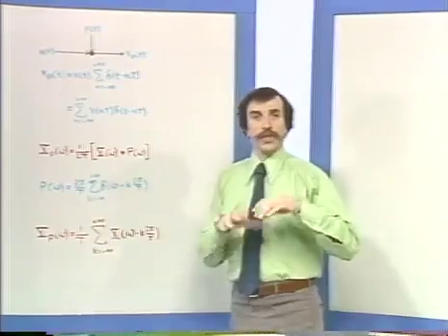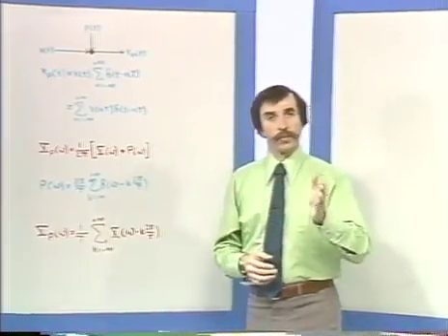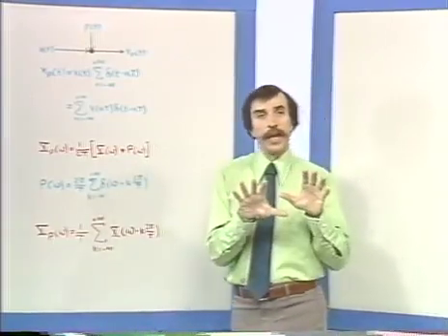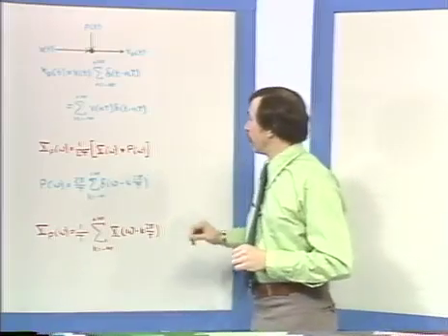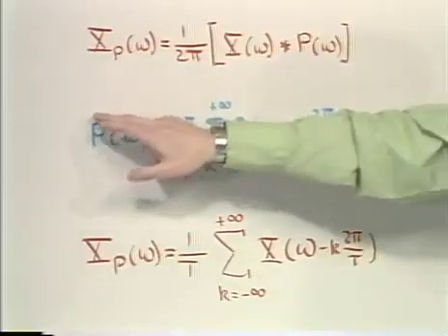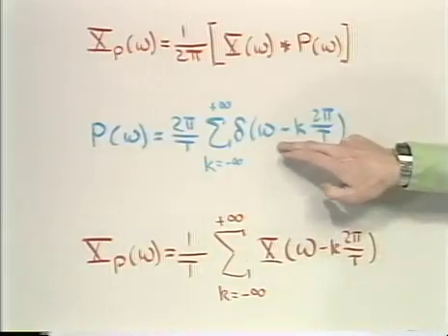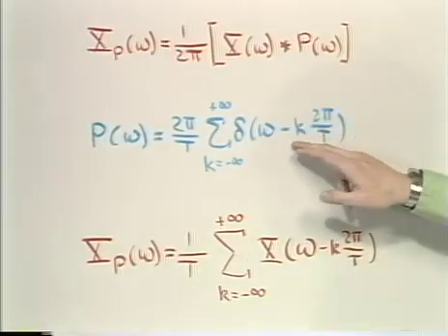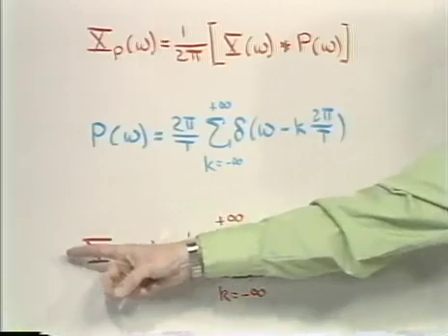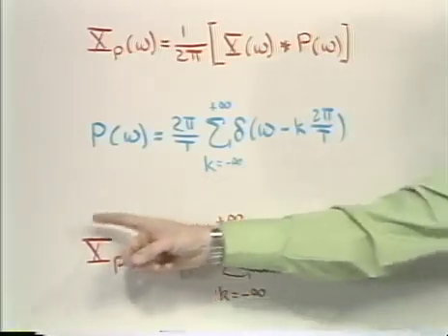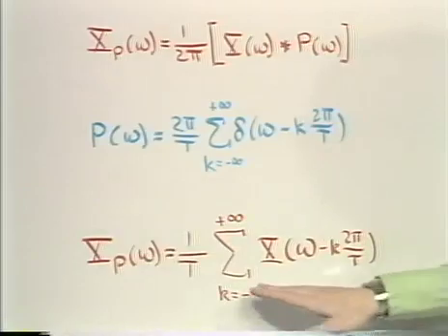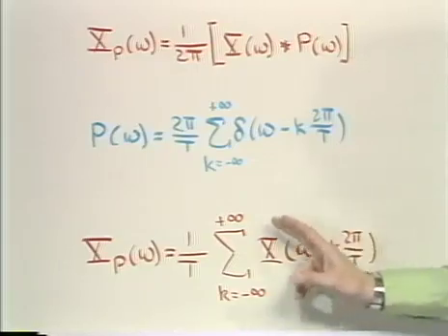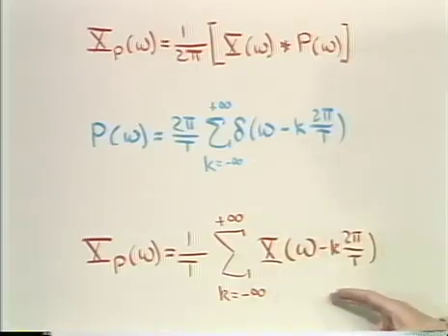Now, the impulse train is a periodic signal. Its Fourier transform, therefore, as we talked about with Fourier transforms, is itself an impulse train. And when we do this convolution then, using the fact that the Fourier transform of the impulse train is an impulse train, the result of this convolution then tells us that the Fourier transform of the sampled signal, or the impulse train which represents the samples, is a sum of frequency-shifted replications of the Fourier transform of the original signal.